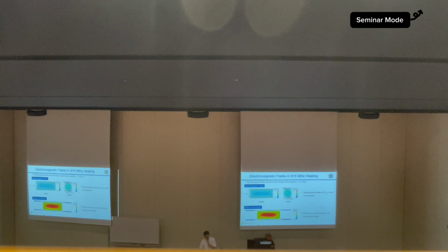And this is the electromagnetic fields in the sample. This is the E field and this is the H field, which shows the electromagnetic fields of TM01δ mode. And this is the power loss density in the sample. Power loss occurs at locations with strong electric field.